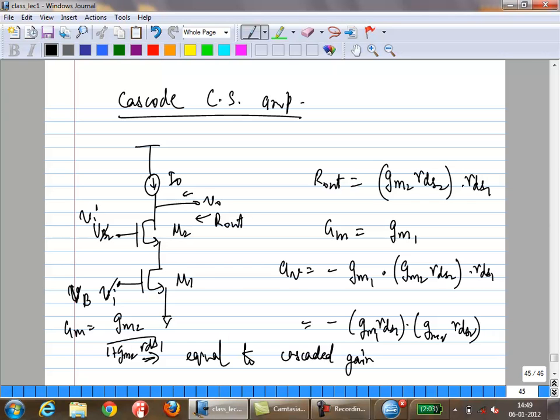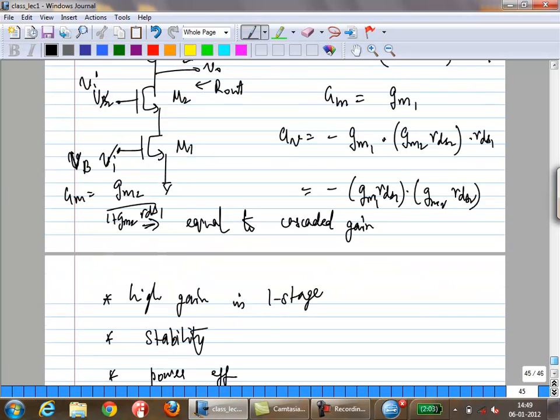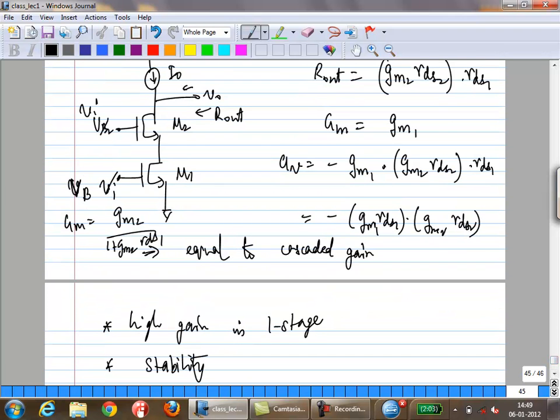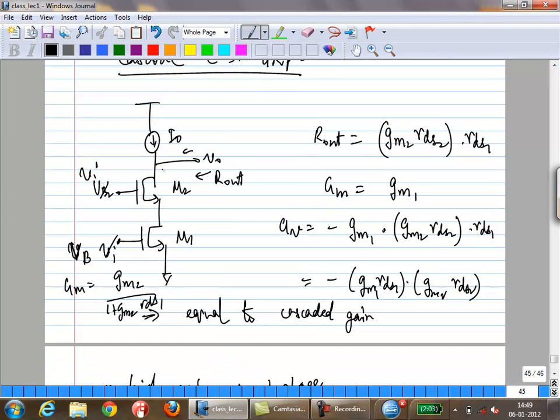Okay, yeah, you're kind of on the right track, but that's not the way I would put it. One of the things is that because you're stacking, you end up stacking two of these transistors. In a real case, if you're using this for an amplifier, you require a certain swing at the output, right? What is the lowest this output voltage can go such that these two transistors are in saturation?